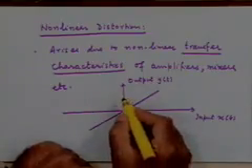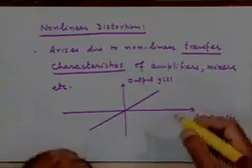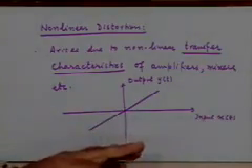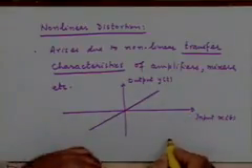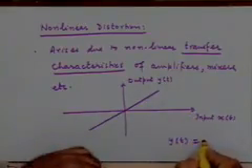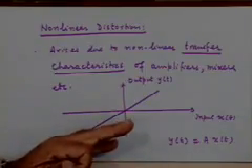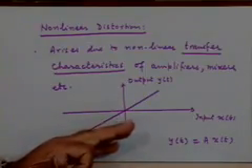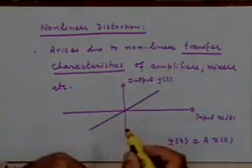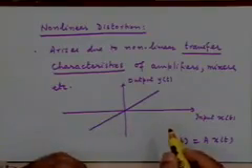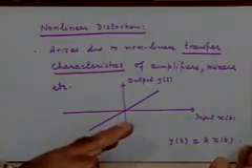Input is small, output should be small. Correspondingly, if the input is large, the corresponding output should be large. Simple. Nothing beyond that. So it's a constant times the input. Ideally y(t) should be equal to some a times x(t), where a is the amplification factor. That's the transfer characteristics.